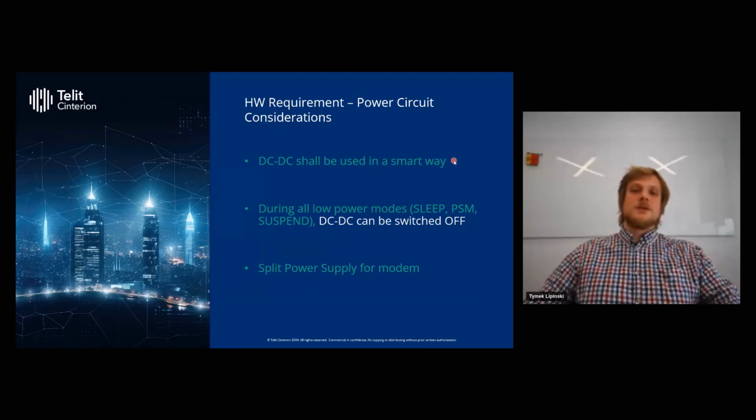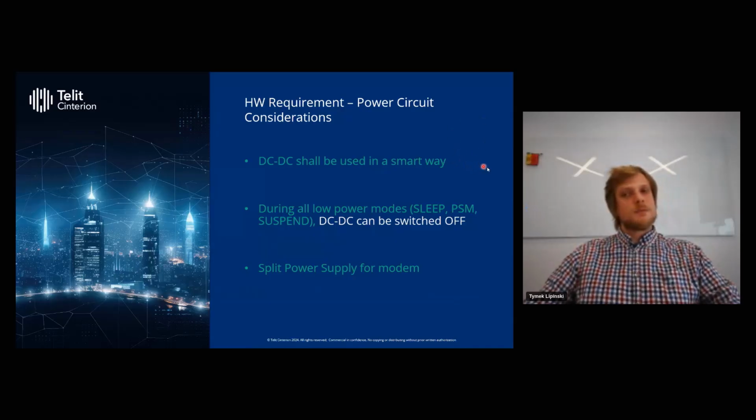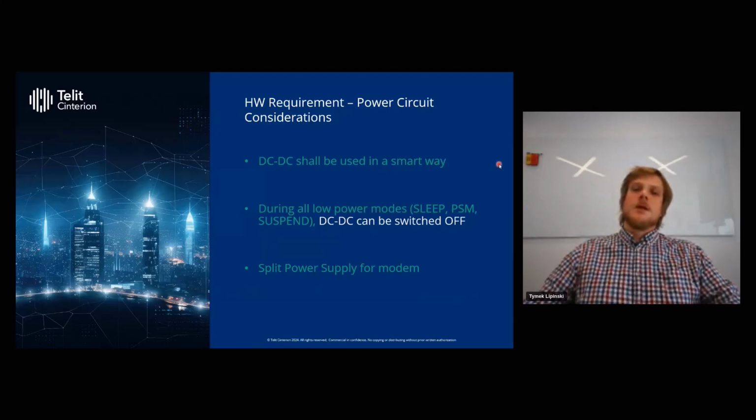It allows the DC to DC converter to lower its quiescent current consumption to a very low value because it's only bumping up the output voltage when the light load is applied to it. So when the module is sleeping, it's consuming microamps, it will be very small current draw. So the DC to DC is a safe keeper of safe voltage level, and it just goes blip, waits, blip, charges up, blip, charges up.